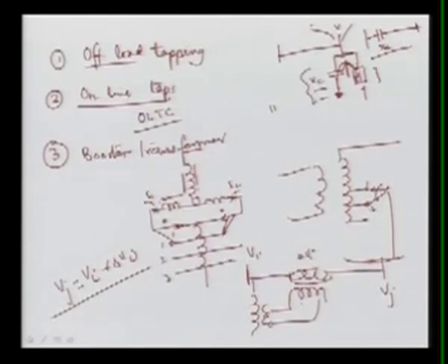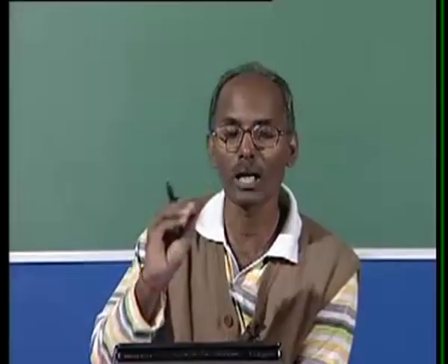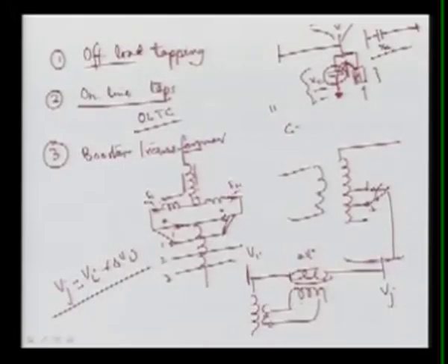We don't require reactive power that flows on the transmission line. So the reactive power support provided by a shunt capacitor, let's suppose for the same C value of 1 microfarad, if you are using it as a shunt for the same voltage bus system, then the reactive power support QC will be larger than the QC supplied by the series one. So always, if your intention is to provide reactive power support, you have to use it in shunt.